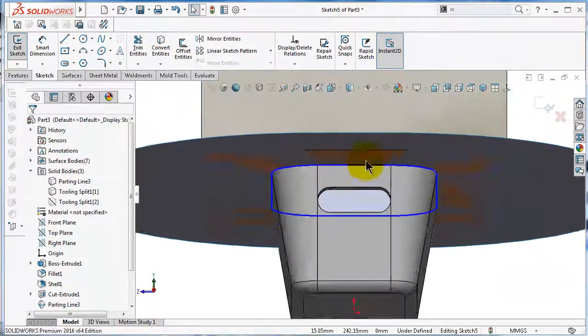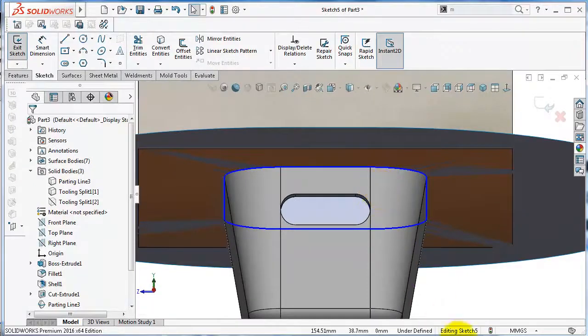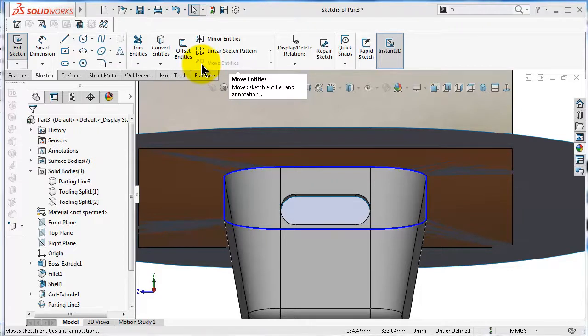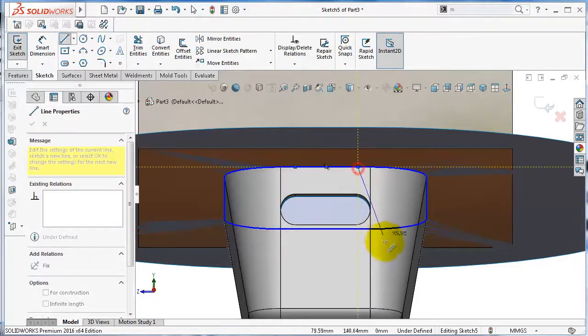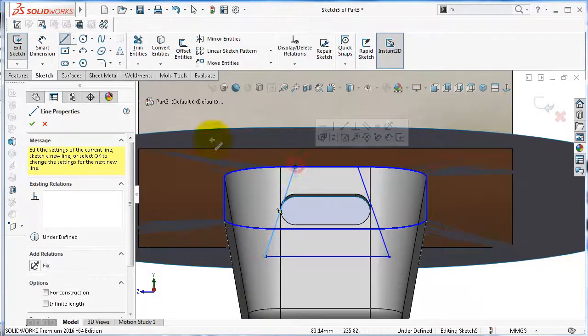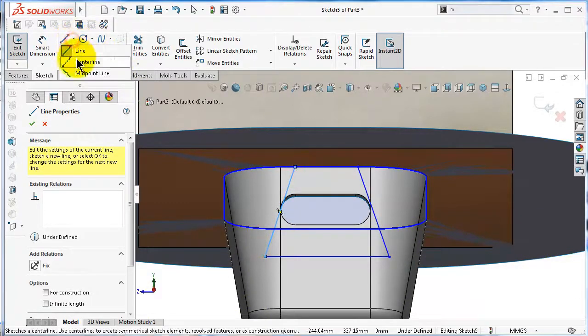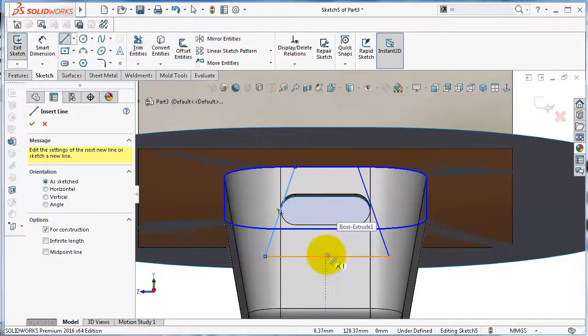Make it normal to, and now we will draw a shape that has an angle so that the side core can be fixed in place in the upper side of the block or on the core. Here I will select the line and draw this shape, center point,